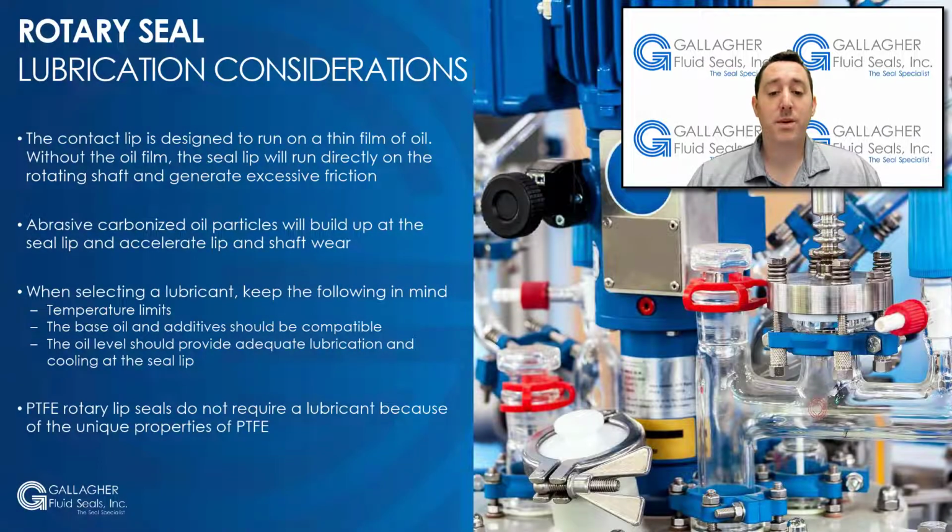The contact lip is designed to run on a thin film of oil. Without the oil film, the seal lip will run directly on the rotating shaft and generate excessive friction, and if the lip is made of an elastomer, could fail within hours. The lubricant selected needs to remain viable over the expected service life.